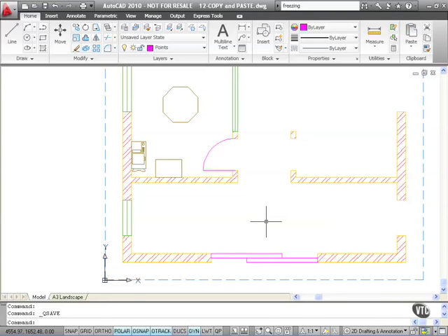Up until now, we've used the AutoCAD copy command known as copy selection. That's this one here. It's on the Modify panel on the Home tab. However, you can utilize the Windows clipboard as well. You can use copy and paste in a way that you would use copy and paste in, for example, Microsoft Word. So let's have a look at how we utilize copy and paste.